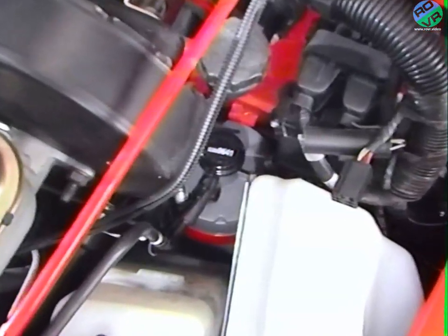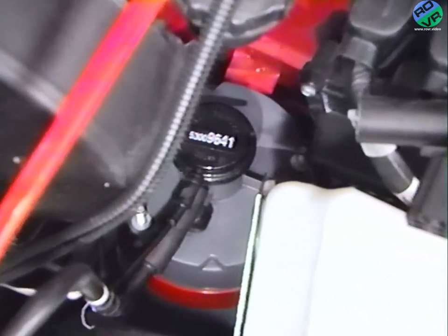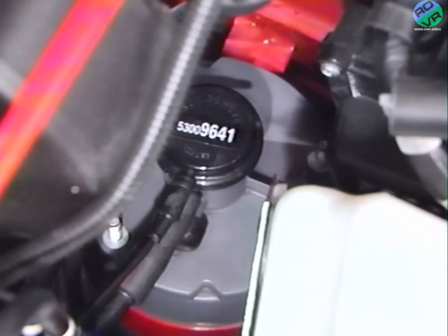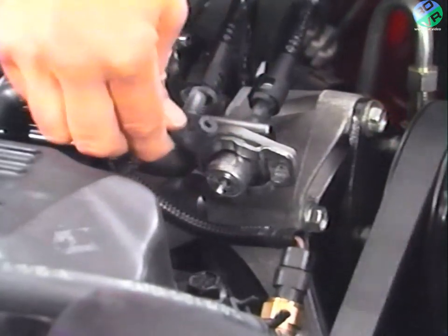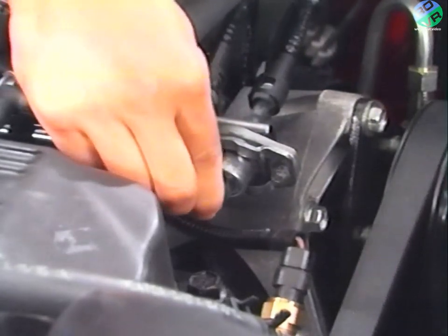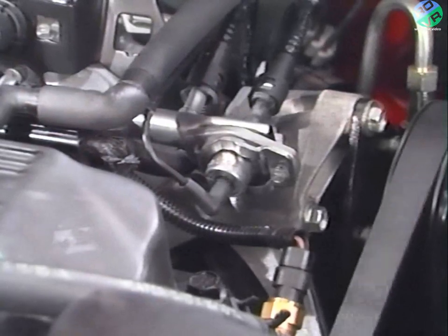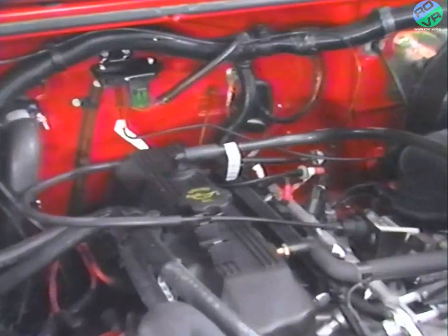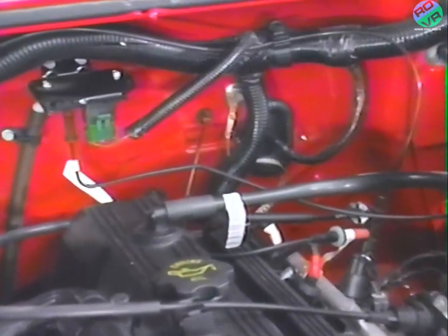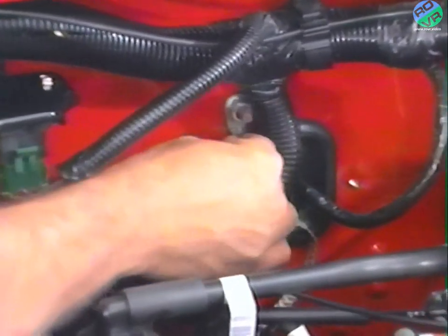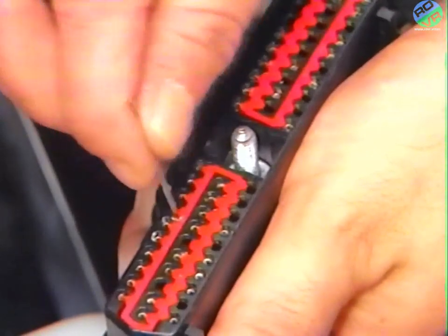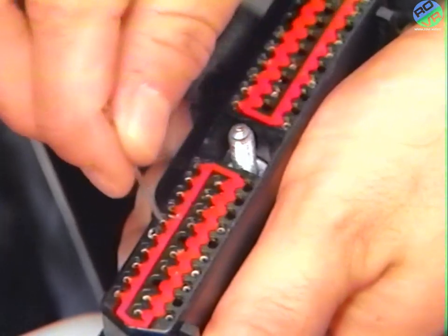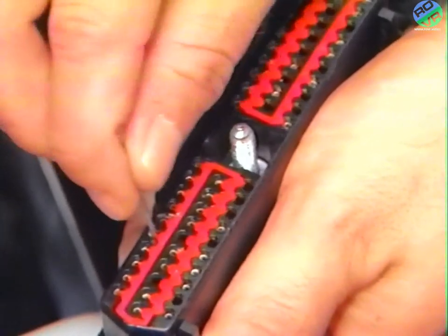The engine controller will not detect a fault in an evaporative purge canister that is restricted, plugged, or loaded with liquid fuel. It will not detect leaks or restrictions in the vacuum circuits of vacuum-assisted engine control systems. However, these could result in the setting of a MAP sensor fault. Poor grounds or no grounds will also not be detected, although a fault may be generated as a result of this condition. The engine controller connector terminals could be spread apart, crushed, or pushed out. Again, this condition could cause a fault to be stored in the engine controller, but the fault would not indicate lack of a ground.